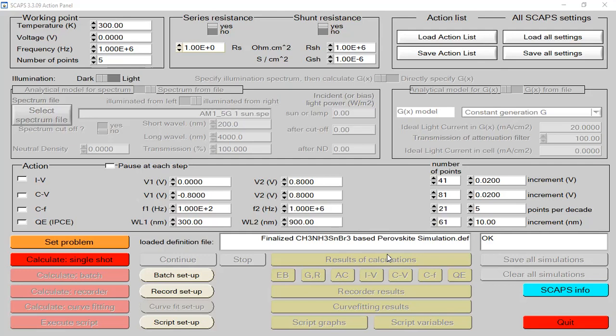So I'm going to start my Nyquist plotting and graphical representation, and I'm going to set my frequency, and then I can explain more important things: how the input frequency can affect the impedance of our device on the real part or imaginary part, how we can plot the real impedance and imaginary impedance graphically, and what is the effect of the applied input signal, higher or lower frequency, on the impedance of my perovskite device. So first of all, we need to mark this button.